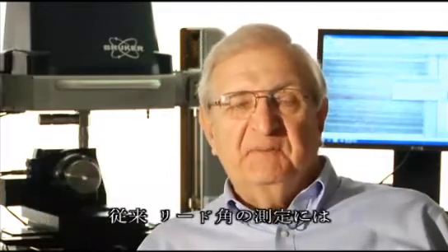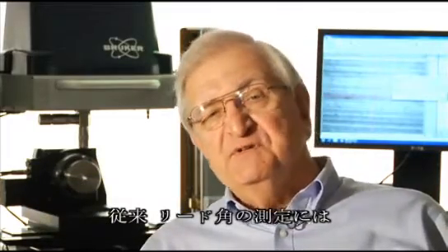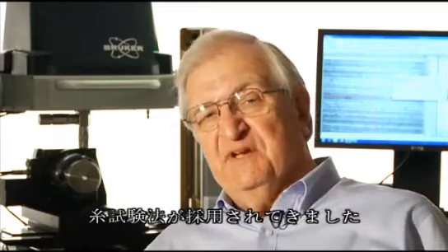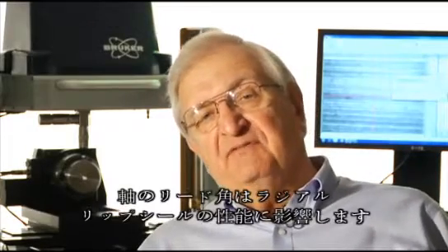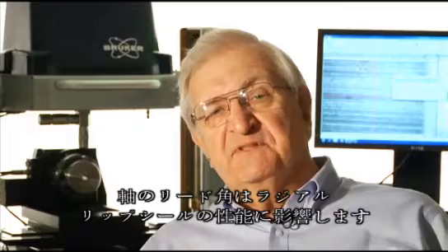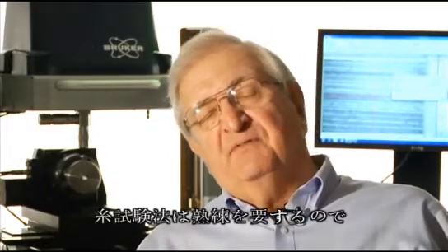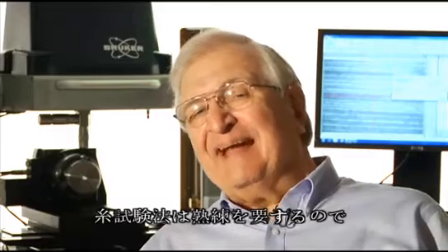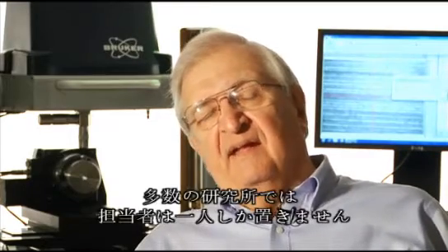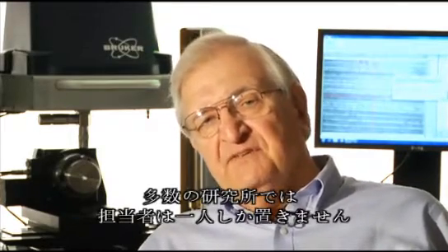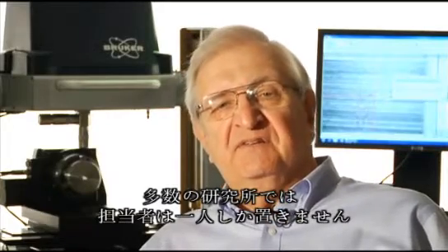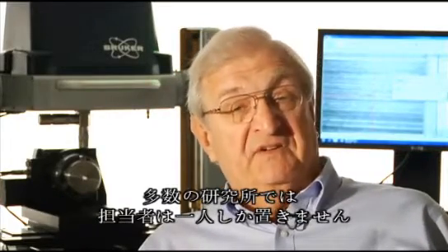And during most of this period of time, we've used a string test method for measuring shaft lead. Now, shaft lead is very important to radial lip seal performance. This type of string test is very technique dependent. And in many locations, only one technician is allowed to run this test.